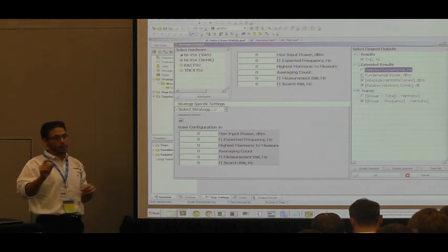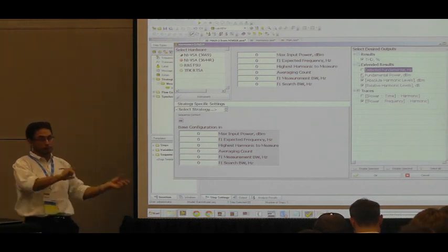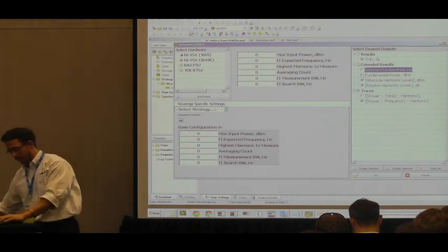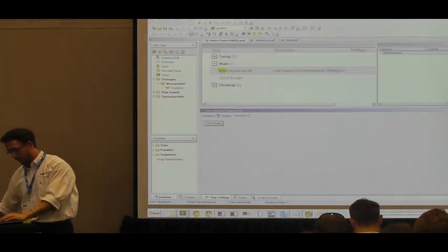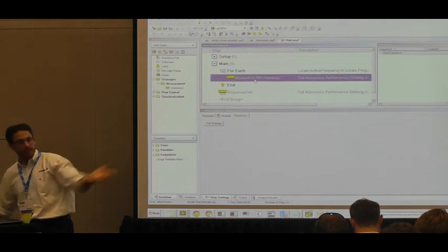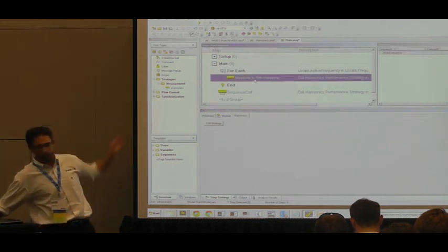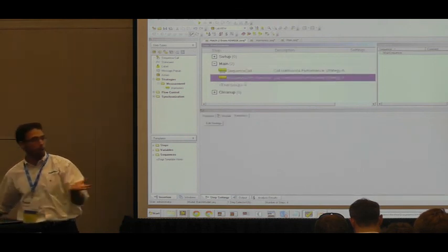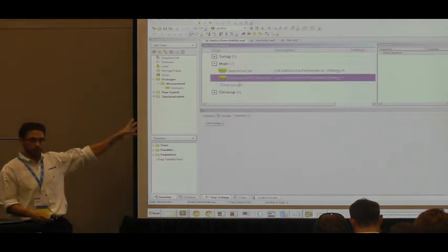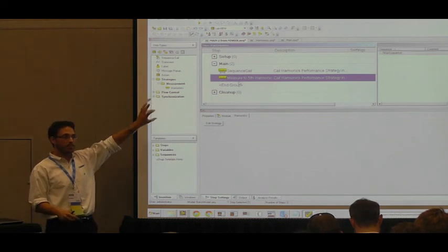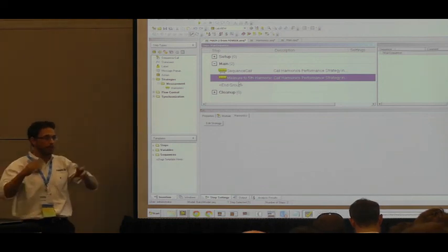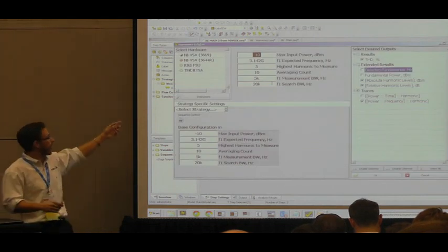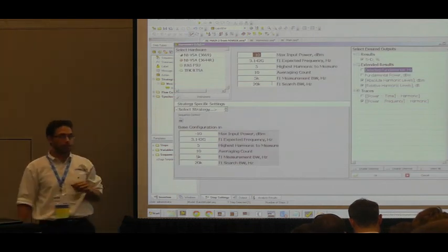Every time that you put the harmonics measurement down and you drop it from the palette, it needs to be configured. I mean, I can take a given one. Let me just do this and see if it's answering your question. I could take this, which is already configured to measure 5 harmonics, and just as easily go here and drop it there, and this will still call that same sequence file. All that this step is doing is holding a configuration so that when I right-click on it and edit it, or when it actually runs at runtime, it has the necessary information.